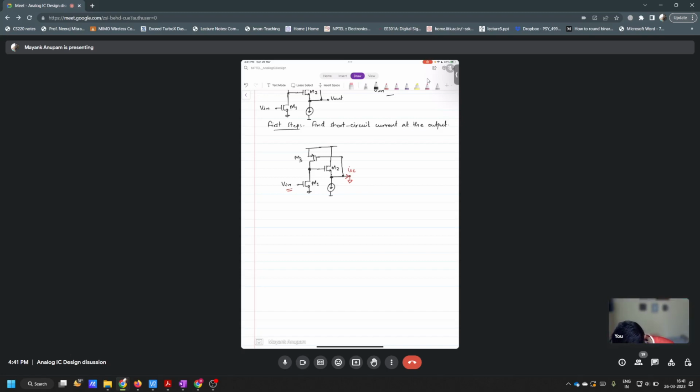This will be minus GM1 times RO1 into V in. Are you sure? Sir, RO3 must be included, in parallel with RO1. Yes, yes, correct.